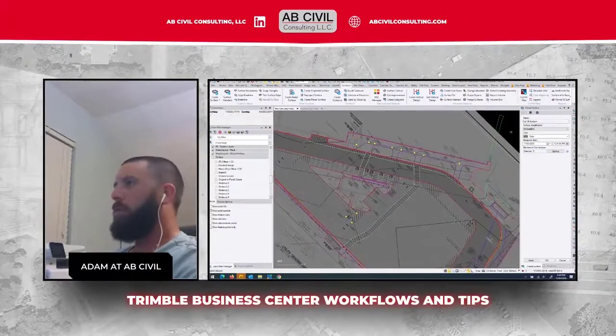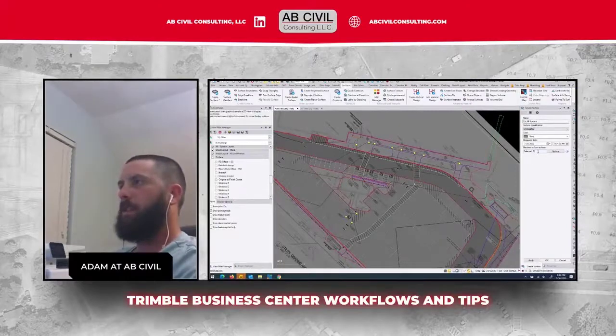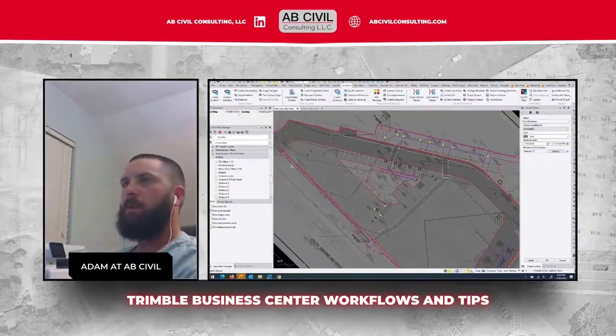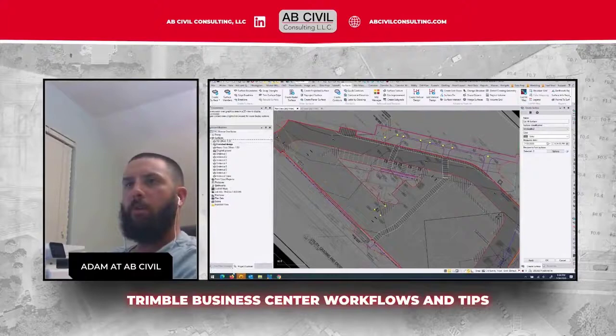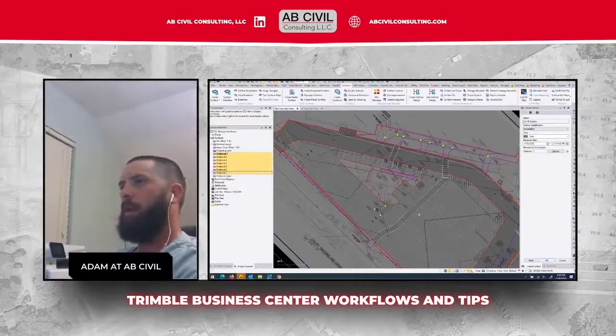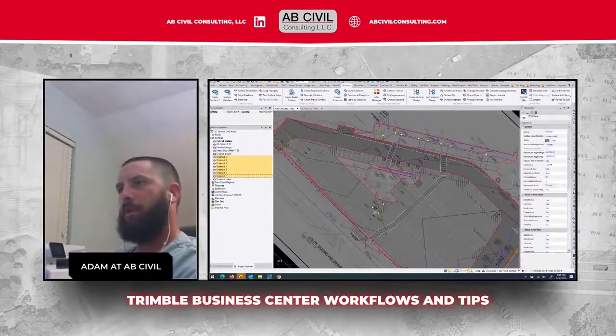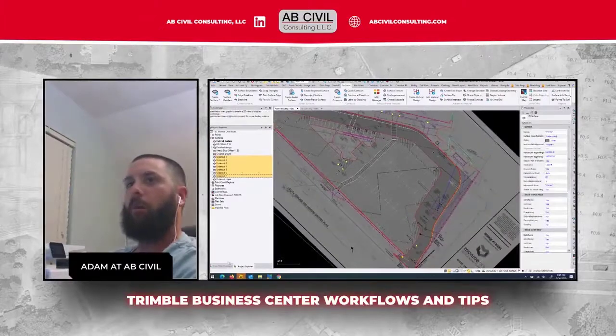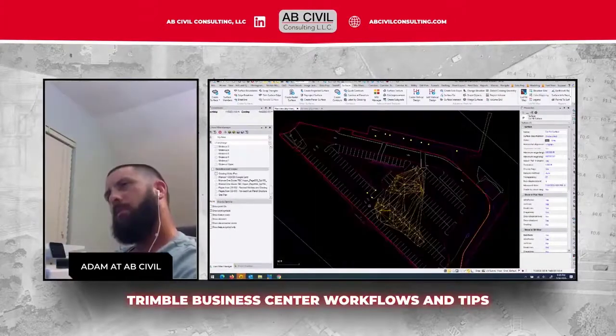So I'm going to do this real quick. Cut fill surface, and in members to form surface, what I'm going to do is I'm going to go to my Project Explorer and I'm going to click Undercut 1 through Undercut 7. So I got 7 members selected. And I'm going to hit OK. So now it actually connected triangles around all of those surfaces.